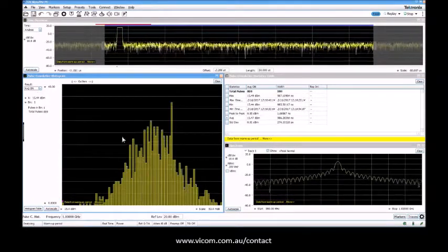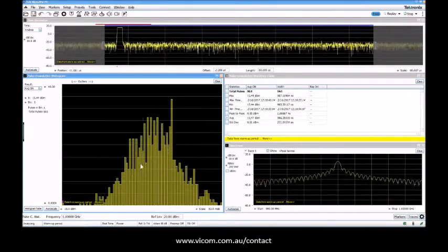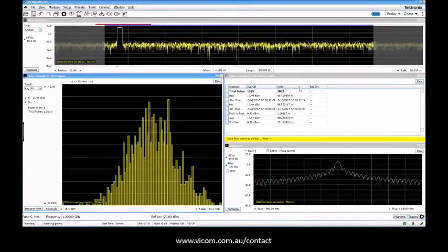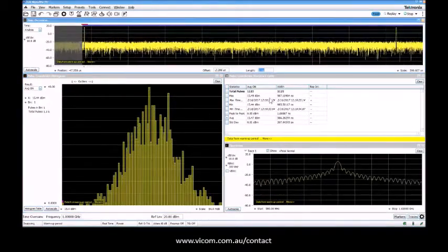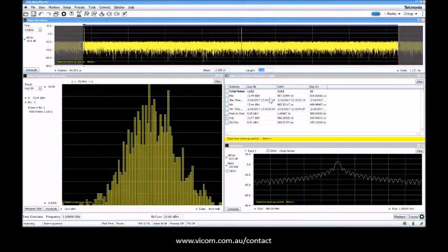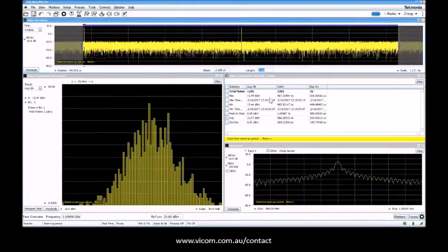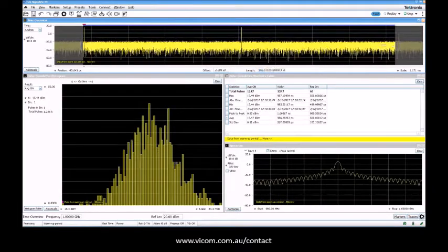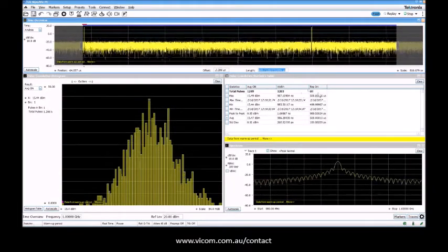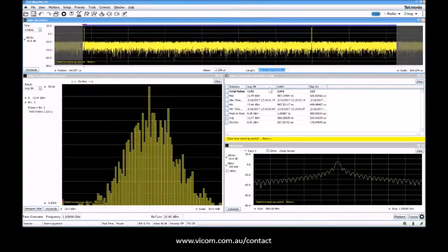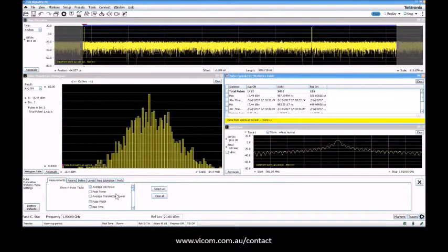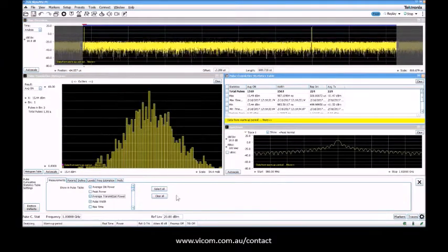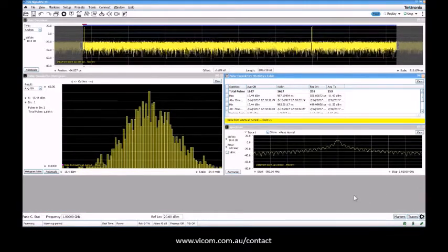This gives you an indication of whether there's something wrong with the simple pulse, but you don't get the pulse-to-pulse information. So I will add a little bit more time until we get a few more pulses. Now you can see that we have 2 pulses, and as long as I have 2 pulses, I get the repetition interval. I can also add another layer here, sorry for this one, to add average transmitted power over the pulses. More pulses give you more.